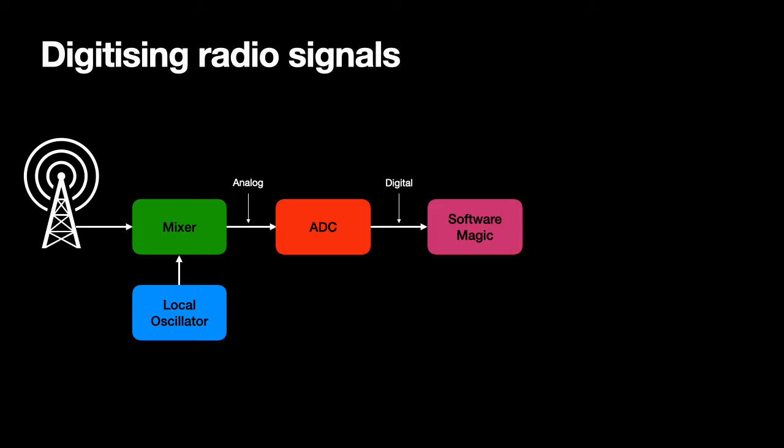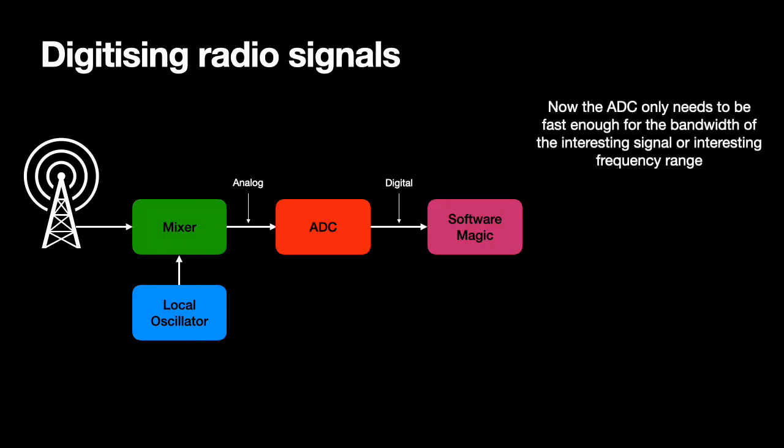So we can reduce the bandwidth required for the ADC by putting back a little analog circuitry. The trade-off, of course, is we can no longer see the entire RF spectrum at a glance, but we still do see the bandwidth of the intermediate frequency. It has benefits as well, including lowering the data transfer rate required between the SDR hardware and the computer.